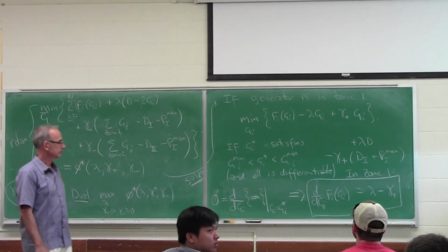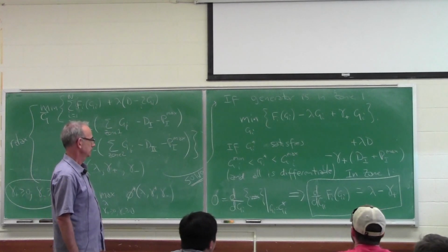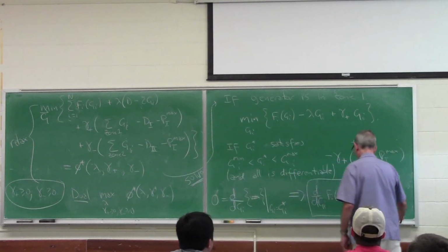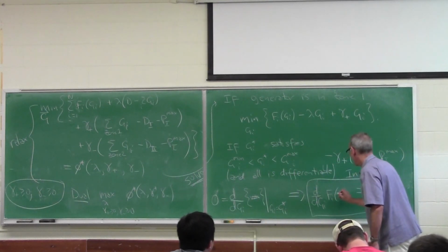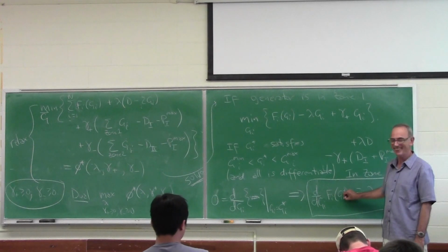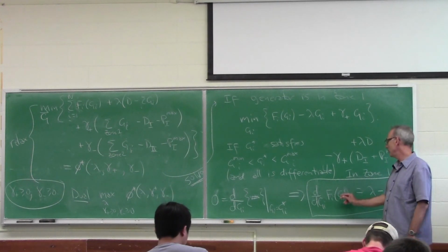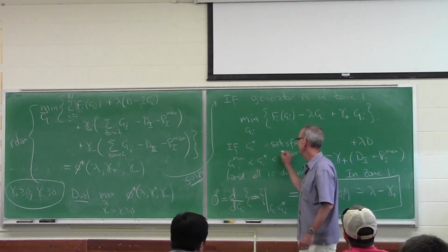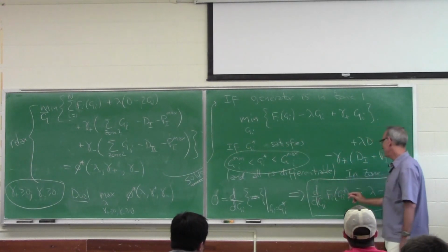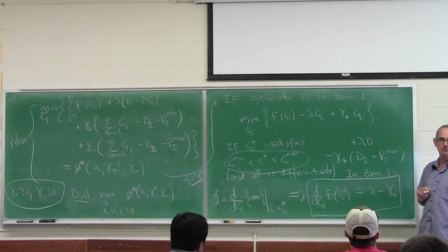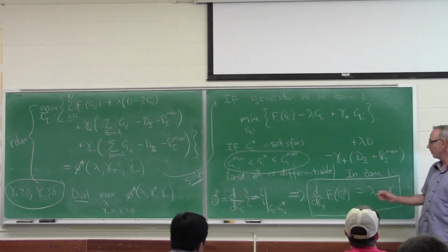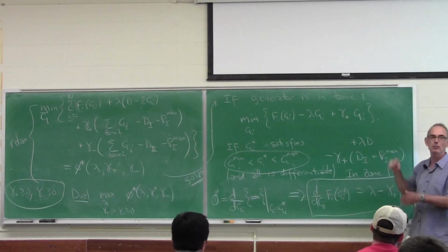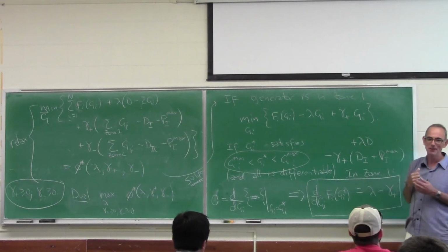Should that mean, you said GI equals GI's asterisk? Oh yeah, this is at the optimizer. I should say, well, yeah, put a space there. Evaluate at the optimizer. The decision we make, the amount of generation, is going to be such that again, subject to this constraint, everybody's going to be set so that their marginal costs are the same. Now again, if this is small enough, then it's got to be operating at minimum. And if this is huge, it might be operated at max, because the boundary optimizers we have to worry about